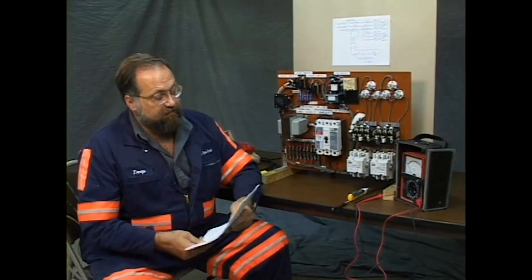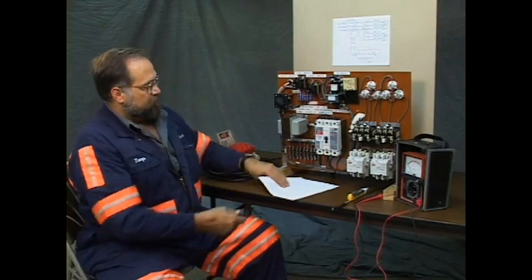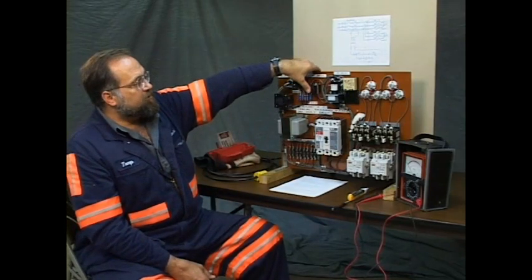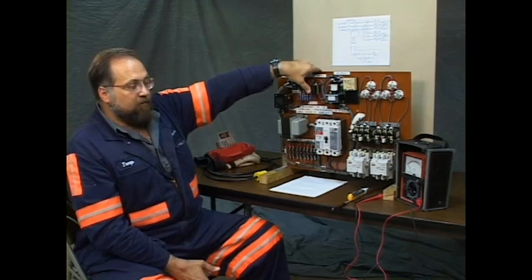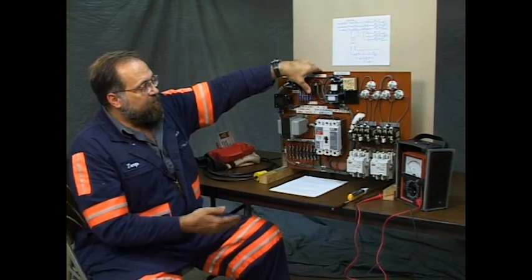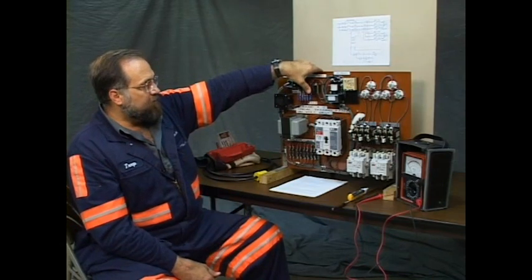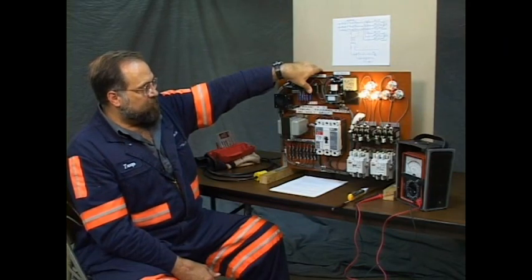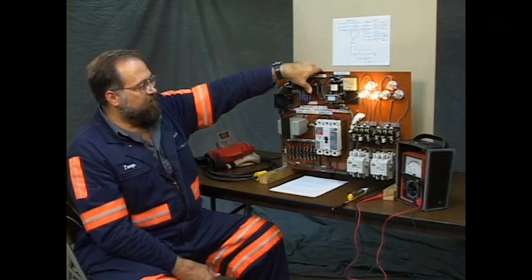Let's try that and see if that's indeed what it's doing. I'm going to press the start switch and A should go, and after the proper interval B should go. The problem says that B's not going at all. Let's see. Now I believe the interval's passed, no B. Okay, it's as reported. B's not going at all.